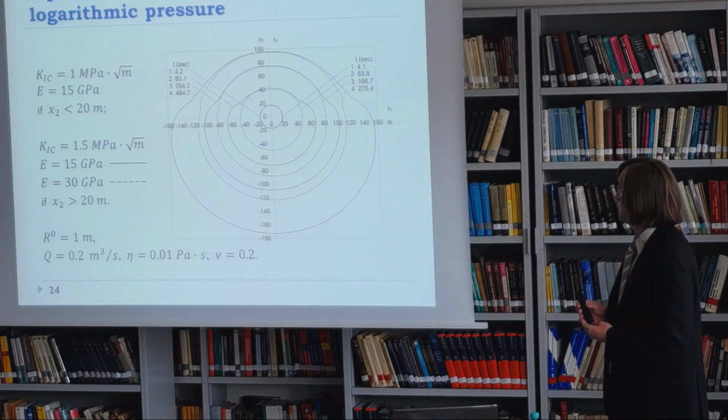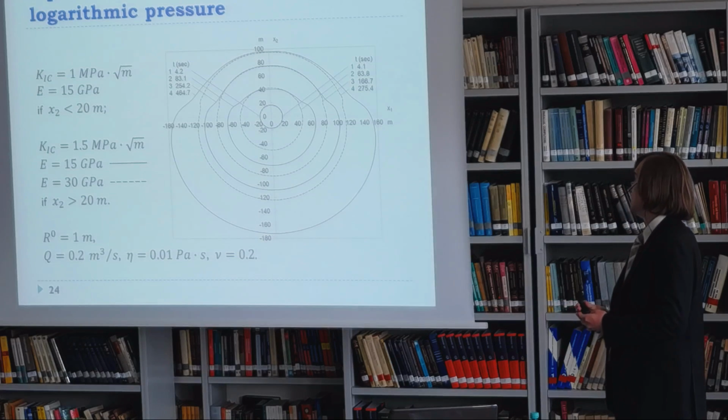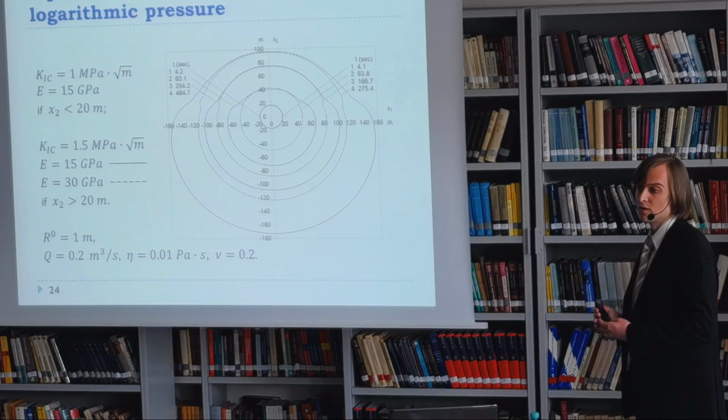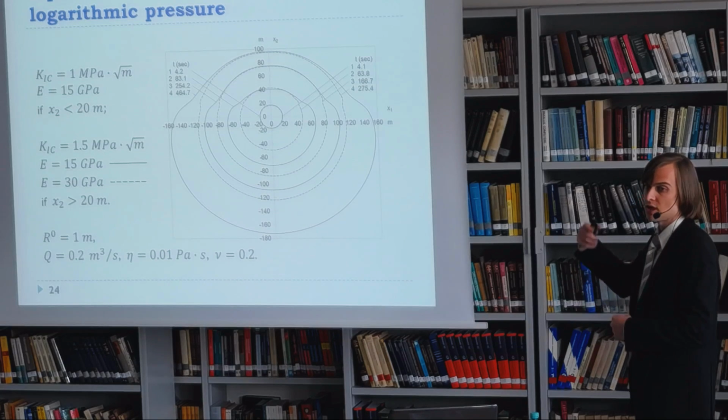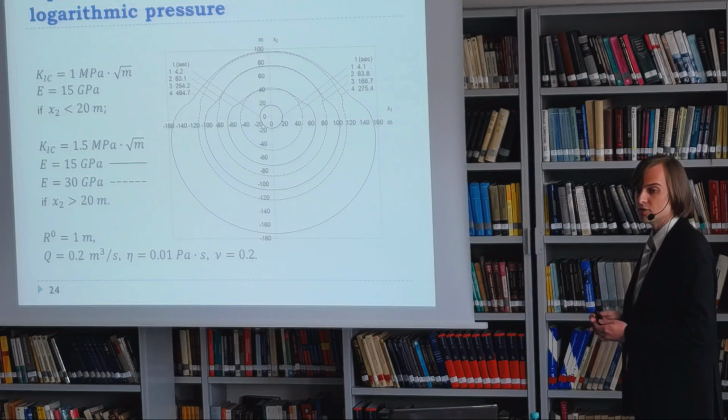But we have found that if both the fracture toughness and the Young modulus are proportional, the crack is close to penny-shaped. The equilibrium crack shape becomes close to penny-shaped. But in the case we leave only fracture toughness variable, it would have an irregular shape, which was a very interesting result.